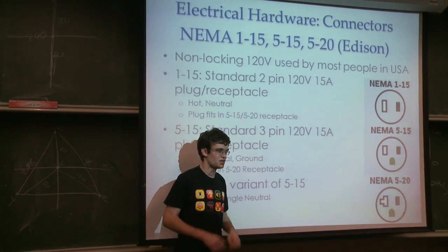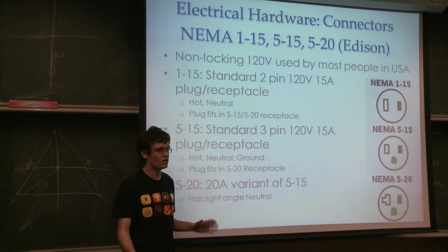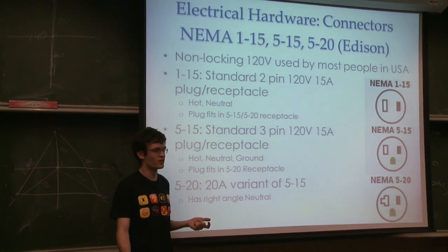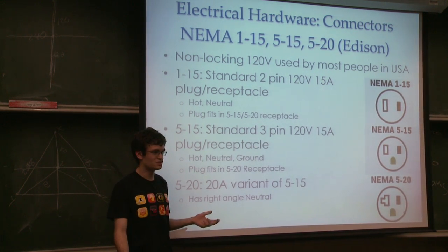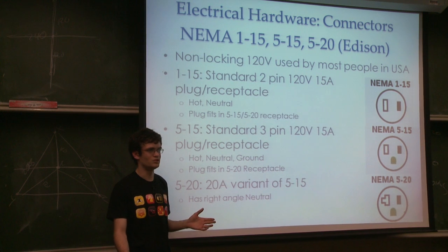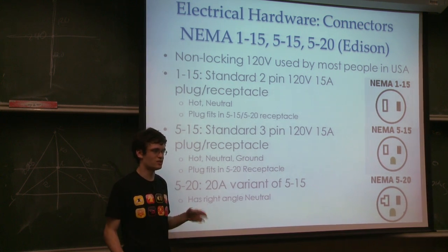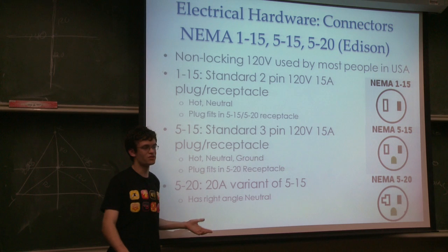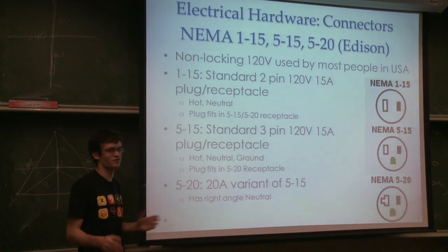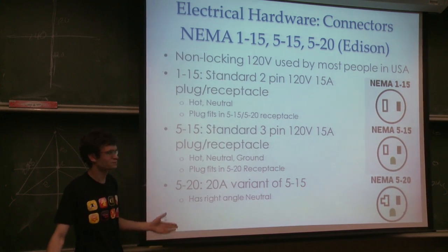Usually. Usually the case of a metal device will be all connected to ground, so if there are any wires that somehow get loose, instead of shorting to open space or to you, they short to the body, which will then go to ground, hopefully through a low resistance path, so it is the preferred path for the electricity to go through.